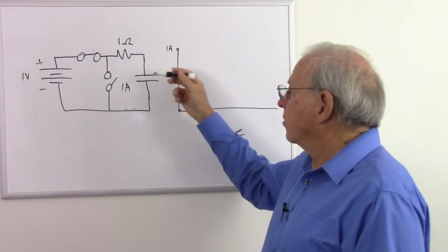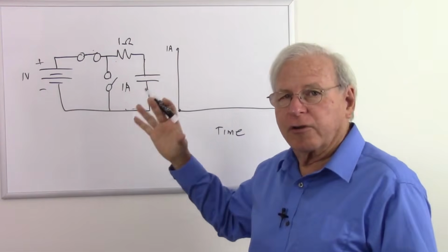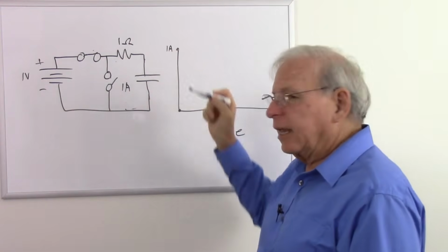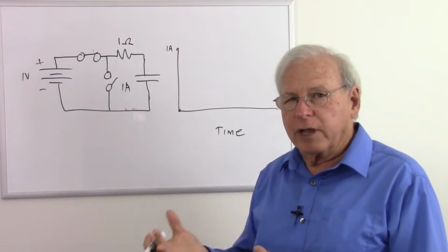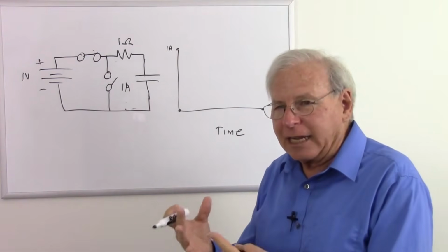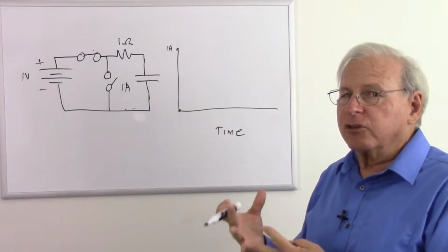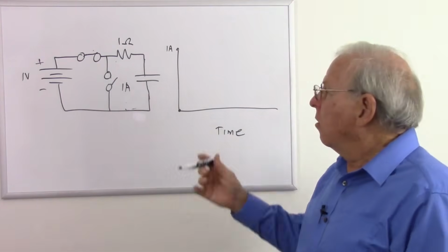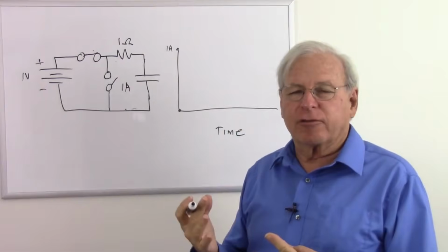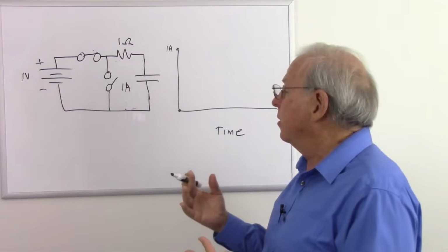A capacitor works the same way, except of course our pressure is voltage. So we put a little electricity in, we get a little voltage. Put more in, we get more voltage. And we keep adding electricity, we keep getting more and more voltage until either we can't push anymore, or the insulation breaks down and the capacitor fails, and it could actually even explode.